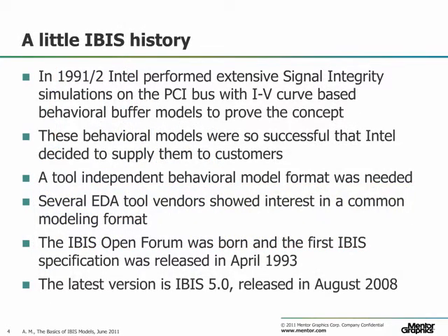One of my first jobs at Intel Corporation in 1991-92 was to perform all the signal integrity simulations for the PCI bus. A lot of these simulations were performed before we had anything designed into silicon to prove the concepts of the reflected wave switching PCI bus. We knew how the main buffer characteristics could be described with IV curves and edge rates, so we decided that we would make behavioral buffer models to be able to perform these simulations.